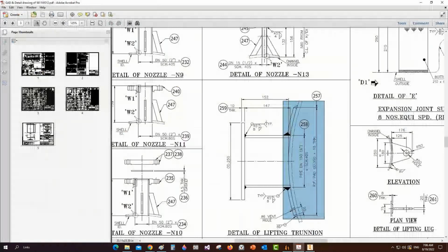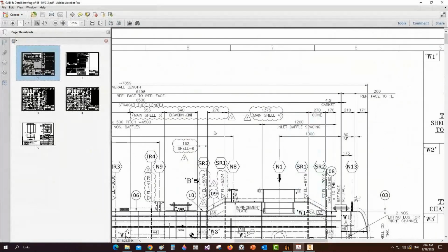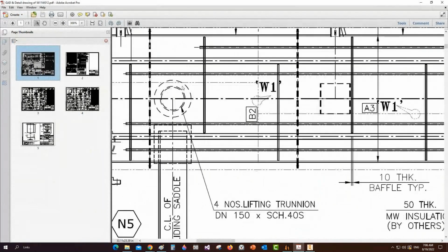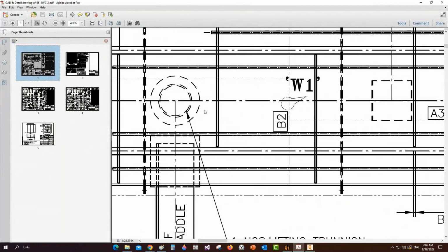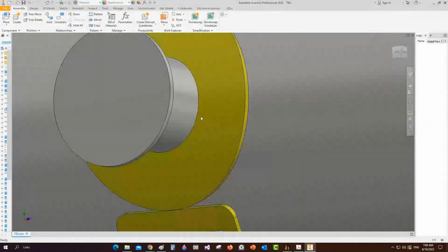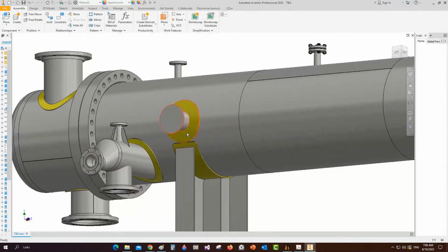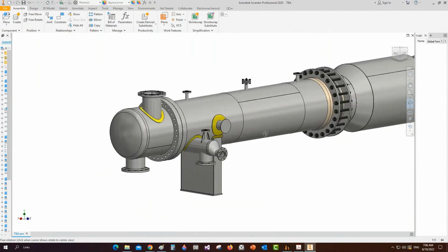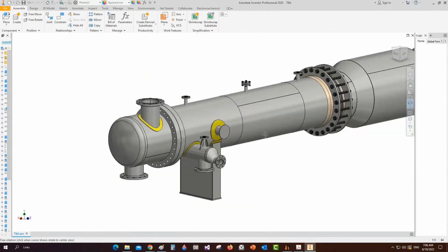If you take a look again here, the diameter of this hidden or dashed line is for the outside diameter of the end plate, not the rebar. So here we can figure that we have a clash or interference between the trunnion rebar and the saddle rebar.